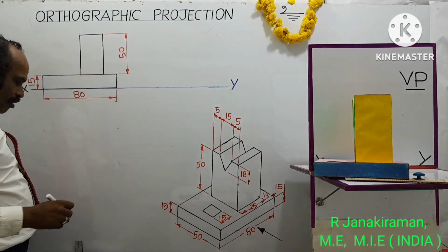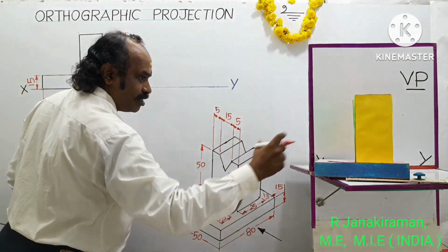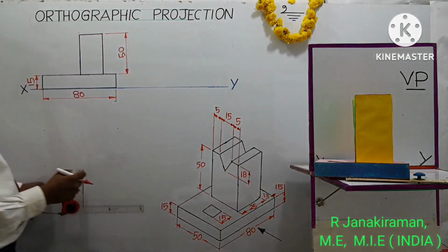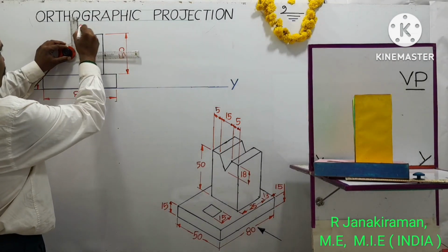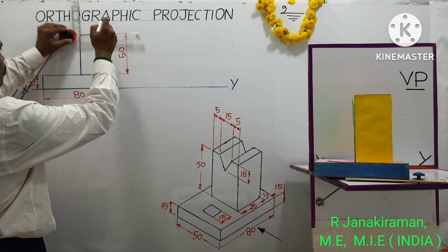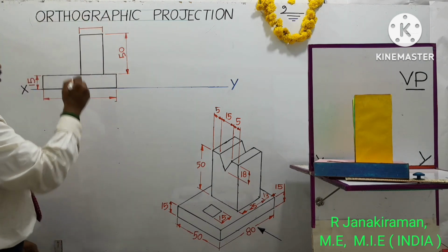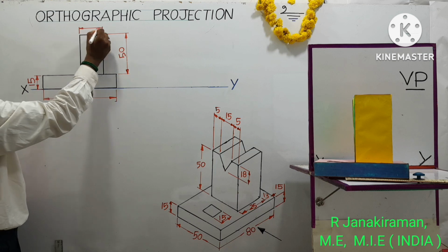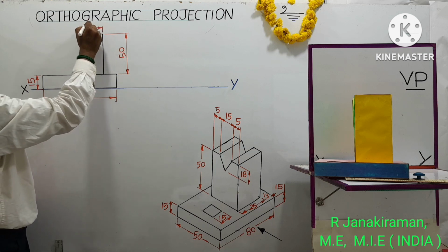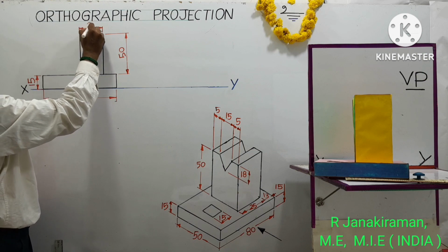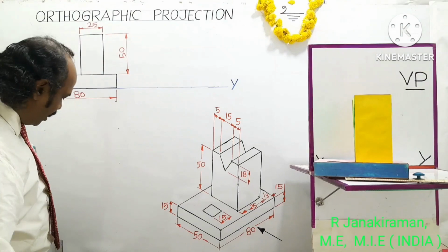Okay. And the top surface, this distance is the same as 25 mm. The yellow color portion is a square of this rectangle drawn. 25 mm shall be written. Put a narrow arrowhead, shade it, and you can write it at the middle center of the dimension line, above it, parallel to it. Okay, 25. Then use a 2H pencil for drawing projection lines.